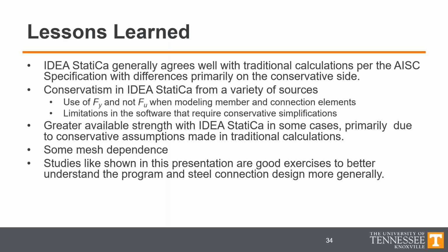So to summarize all of what I've been talking about, IDEA StatiCa and the underlying CB-FEM method really form a rational method of connection design. And while not a replacement for engineering judgment, really safe designs should be expected for properly defined models using the default analysis and design parameters. Care is going to be required when defining the model to ensure that the behavior of the connection is as intended. And there are some other conclusions as well, in terms of some common sources of where conservatism in IDEA StatiCa comes from, as well as some common sources of where IDEA StatiCa gives greater strengths than the traditional calculations.